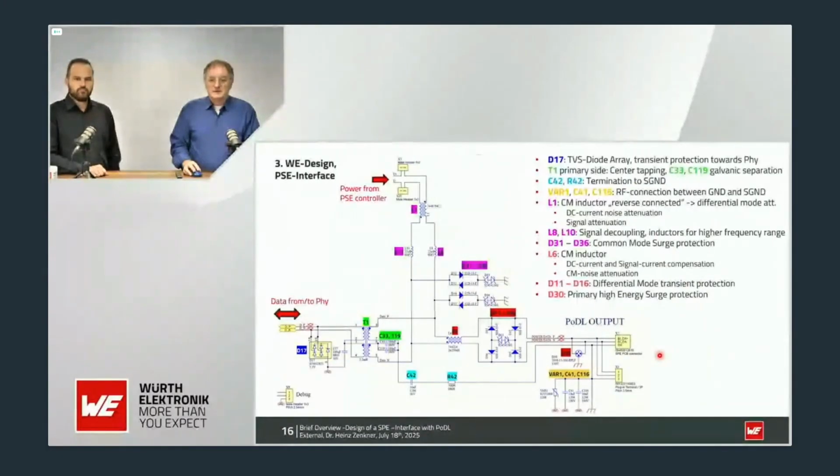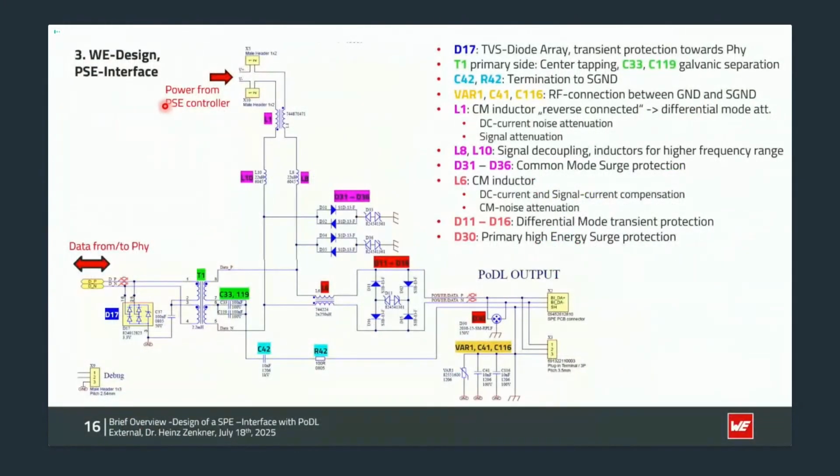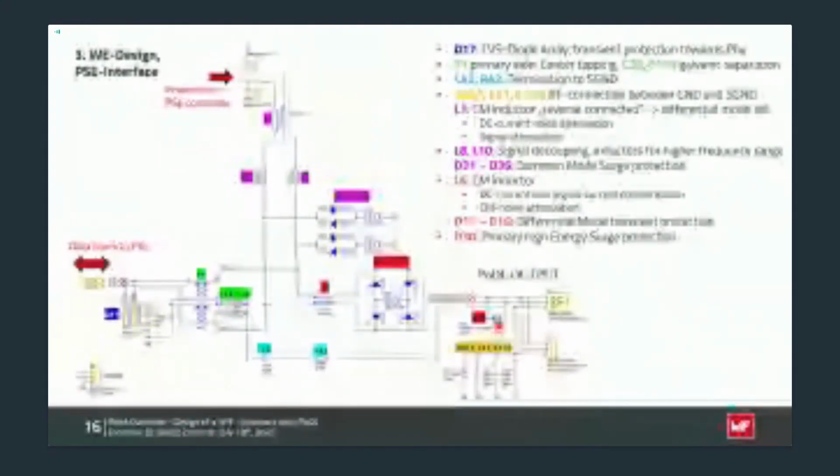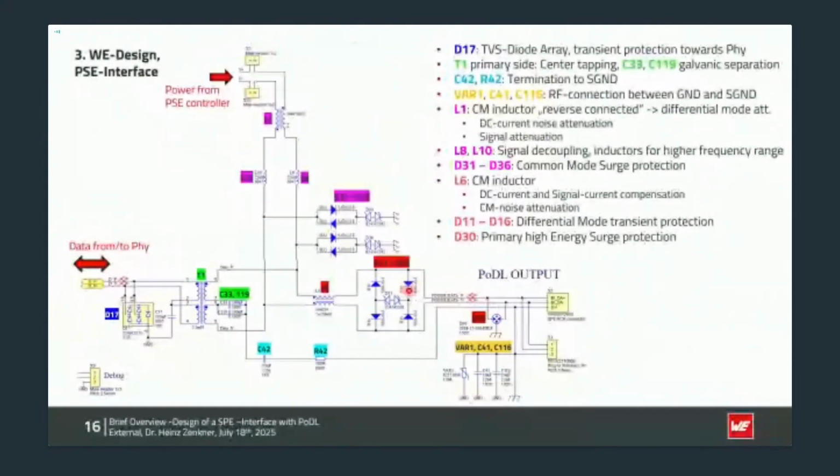So again, a little bit of detail here of this schematic of the PSE, and I have told you already that's the same at the PD side. But here we incouple the energy coming from outside, from the power supply, going through the controller, and it is decoupled here again in the higher frequency range, and going here through the common mode choke out to the PD. You see from the other side coming inside, we have the gas discharge tube here to limit the first, let's say, huge energy impulses going to the differential mode clamping here.